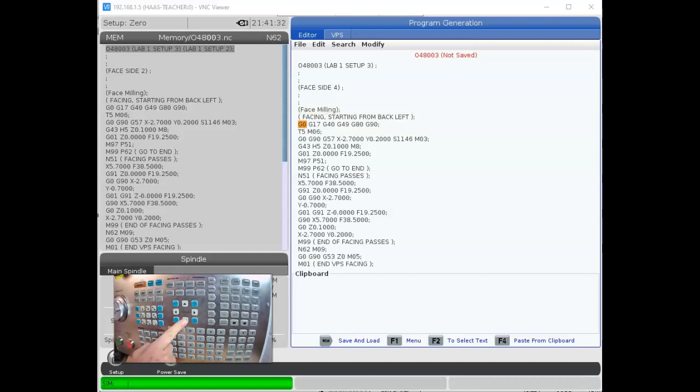Everything stays the same except for our Z depth, which is here. So now we're already 10,000ths under but that lined up with Z0, so now this Z should be minus 10 thousandths. And I should have hit an alter, but I forgot, so I just hit delete.